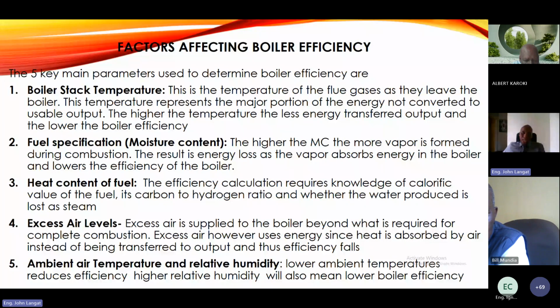Also, I've done a table below here at the end of this presentation, which shows the moisture content and how much calorific value each biomass has. These are records that you need to check, and see how they've been consuming and utilizing their steam. For this one also, you need to go back as an energy auditor and check: are they storing their firewood or their biomass in a sheltered place, free from weather vagaries, especially rainfall?